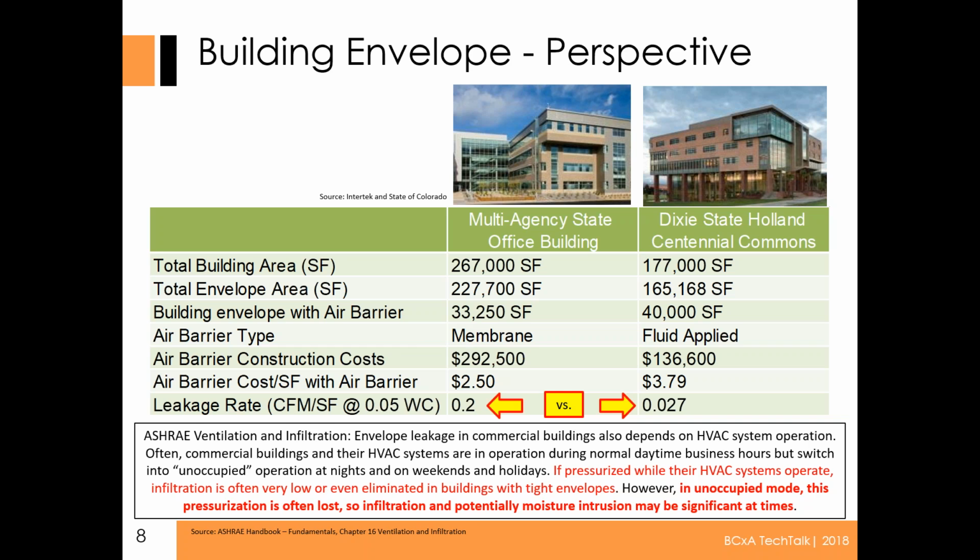So if you're in an environment with lots of hot, lots of cold, you're going to need to have extra outside air to create a positively pressurized building. And if you look at these two buildings, it starts to give you an order of magnitude that shows you how extreme and how much more outside air the building on the left would actually need to be positively pressurized.